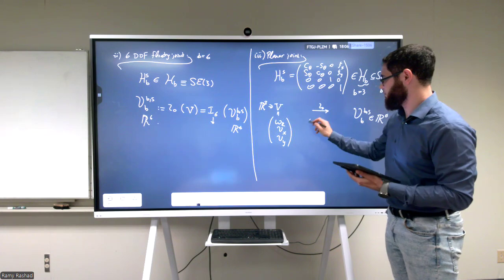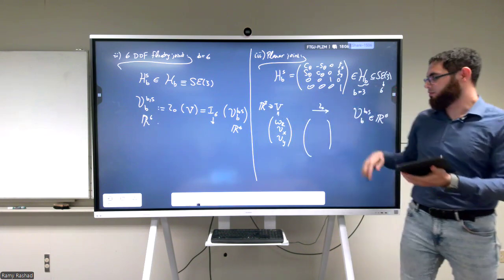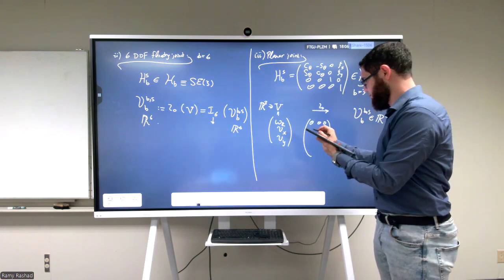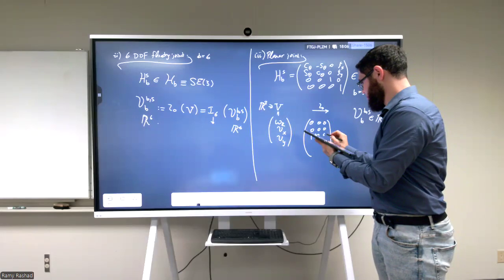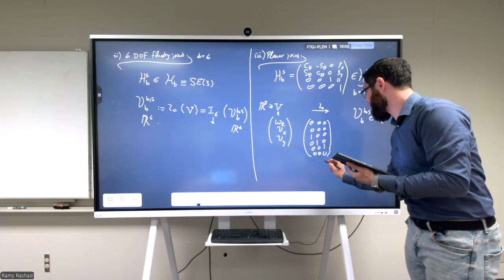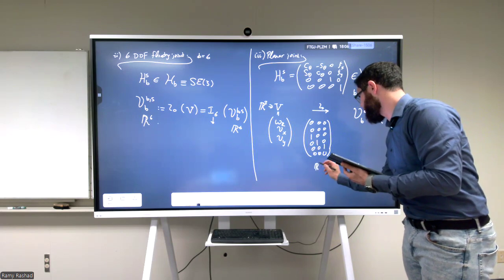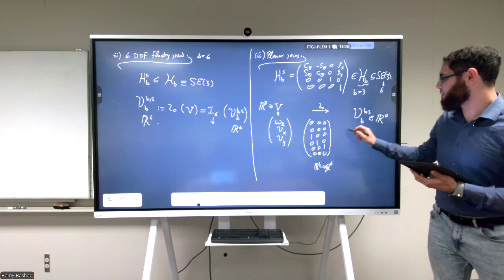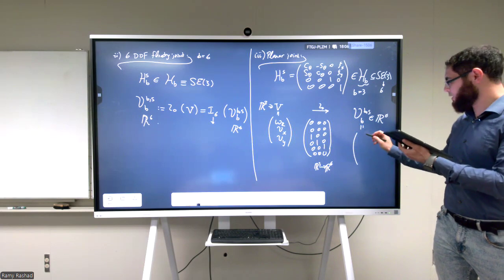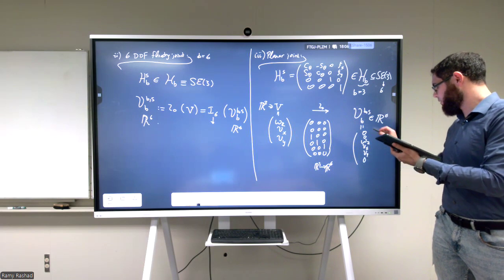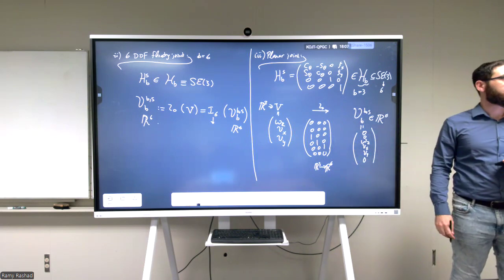So I'm going to multiply this, not from the right, from the left. So this should be here, and I should multiply by this guy. This is a map that eats something in R3 and gives you something in R6. And in the end, the twist will be equal to 0, 0, omega in Z, V in X, V in Y, and 0. Okay?